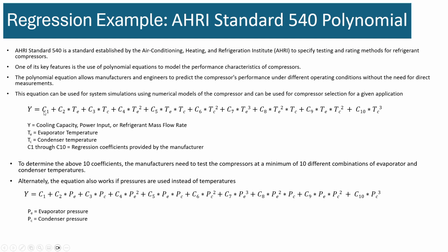Now let's take a closer look at the equation. This Y could be any of these. Cooling capacity, which is basically, I don't know whether you're familiar with BTUs per hour, that's the same as watts. It's the amount of energy it can remove per second, so it's in units of power. So it's watts or BTUs per hour.